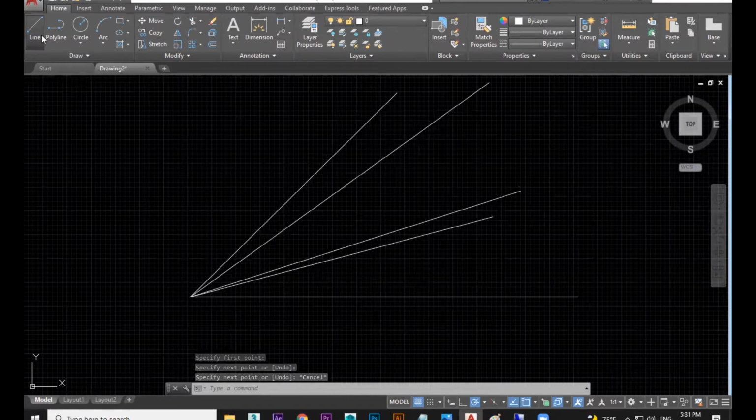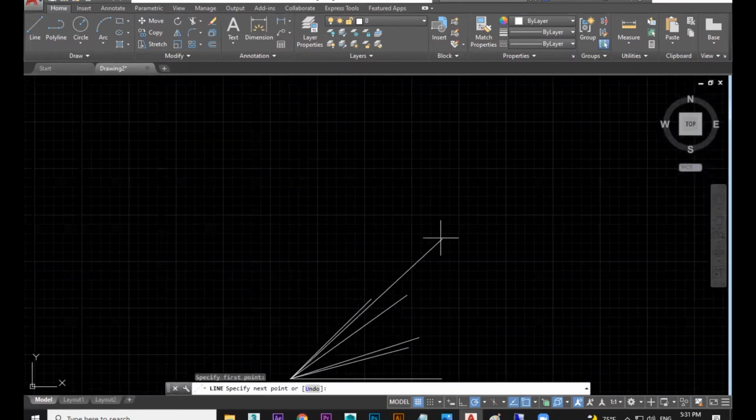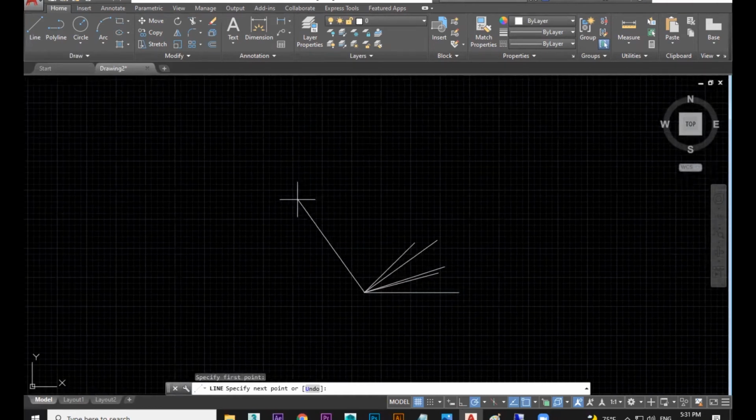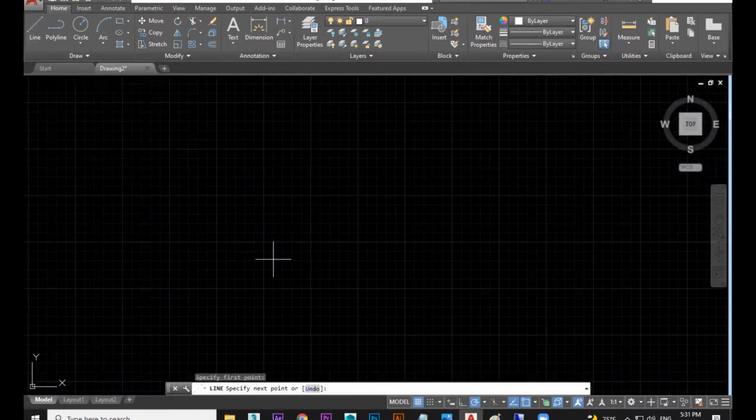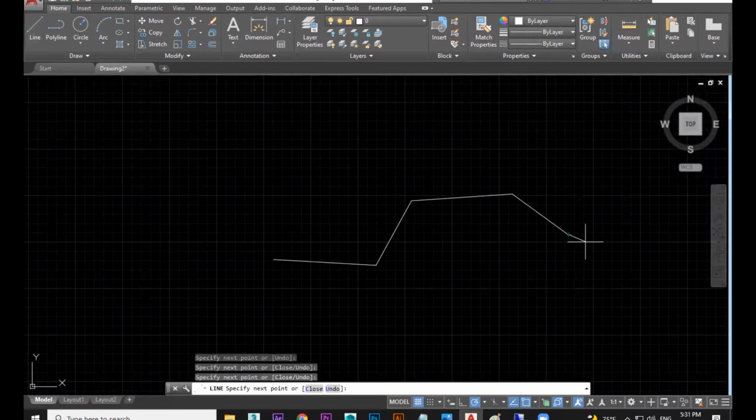When you choose 45 degrees, so 45 degree will be coming from here. You see the green color, it's snapping to you. That's 45. Next is 90. And I go over here, other side, it is 135. So that interval continues. Okay. So you know how to draw with a line tool now, right? When you want to end the line, you need to hit enter.